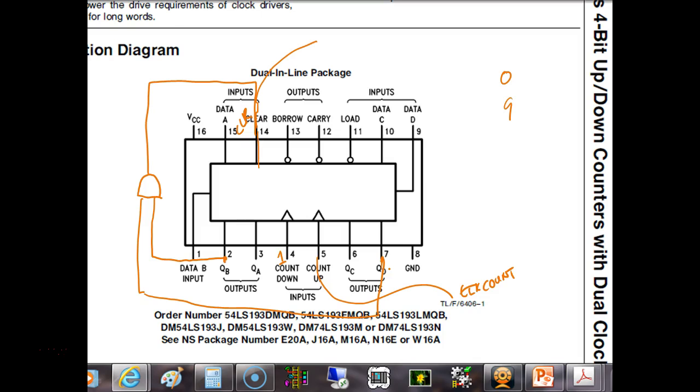Now, what advantage, and you're still going to run into counters, even though with computers we can write a program that counts. So in PLCs, we're not going to wire a counter. We're just going to put a symbol up there and say it is a counter. But it's done by software. To program a 10-bit counter, which could count from 0 to 1024, it might take 100 lines of code to take care of everything that the programmer wants.